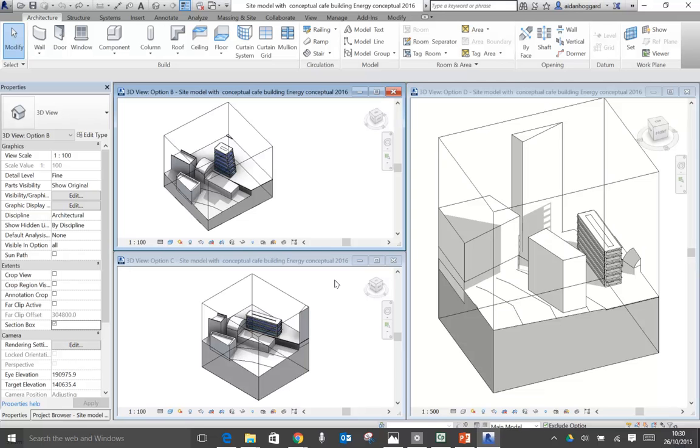It also goes against the principles of integrated BIM, because in a BIM environment you might be working with many other team members. So you can't have multiple Revit files. So that's just the wrong way of working. What you do in Revit is you work with design options. And within the single Revit file, you can have multiple options in the same place, which allows you to test